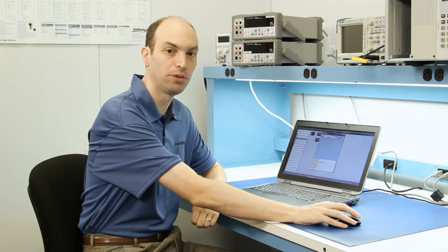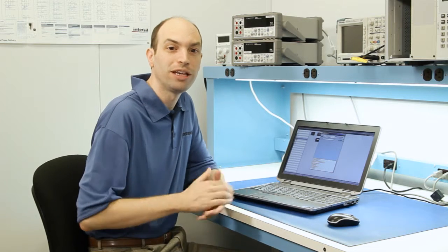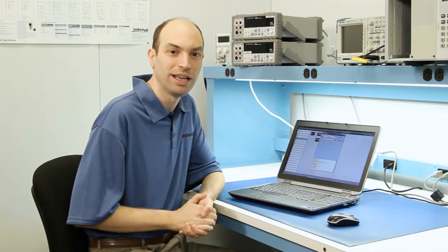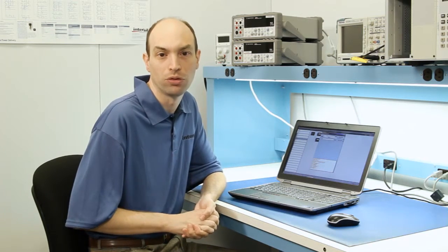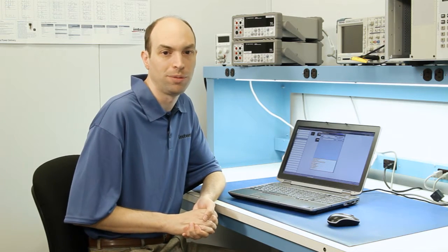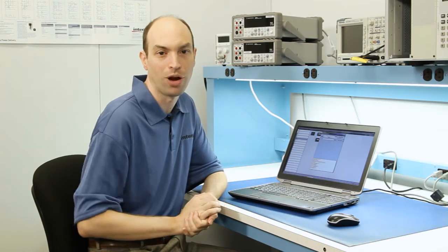If we want to add a couple of different commands on here, we can keep dropping down boxes by clicking that plus symbol, or conversely using that minus symbol to remove them. And now we can add in as many commands as we want if we're quickly adjusting between one parameter and another. The other unique benefit of this command line tool is even with complex commands, it allows you to see all the different bit fields that get selected and set up. That way you're not looking through hundreds of pages of documentation trying to understand exactly which bit controls which parameter.